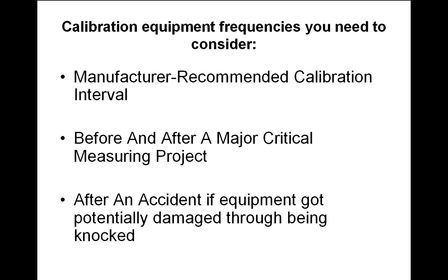You're done for 0 ohms, and that's your calibration there and then. For voltage calibration, there are normally little potentiometers inside the unit you could use to tweak it a little bit. Digital meter, when you open them up, there's nothing there to calibrate it. All you could say is, right, this one is way out, we're not going to use it.